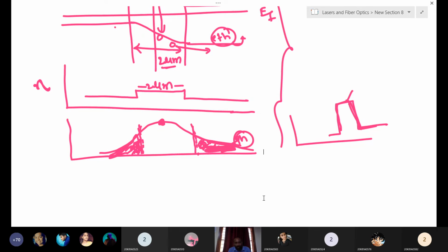So the drawbacks in the homojunction are that the active area is not well defined, the refractive index is the same, and the output laser power is less. There is also a chance that electrons will enter the P bulk region and recombine with holes. That happens in the same material only and is not useful for producing the laser beam. Similarly it happens for holes too. This is the semiconductor homojunction laser.